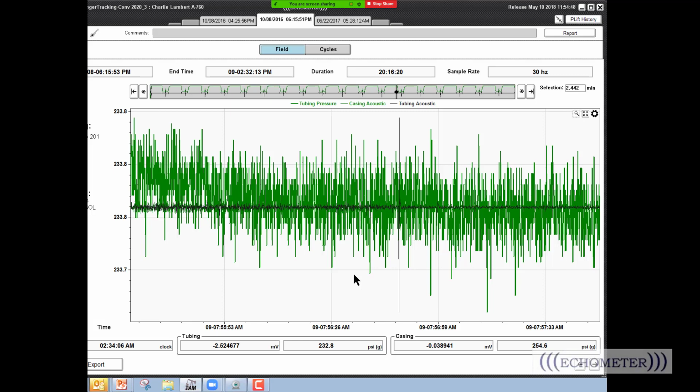Well, let's do this last question asking, how can we know the corrosion between tubing and plunger? I would say that the performance coefficient changes and the plunger velocity changes. The plunger velocity is a function of the gas flow rate in the tubing.